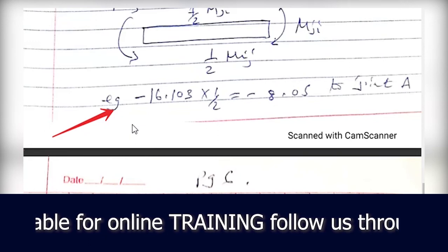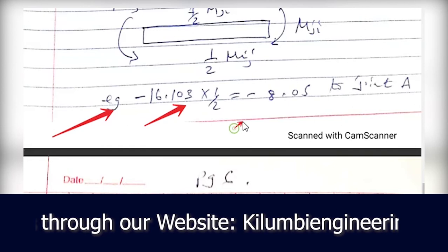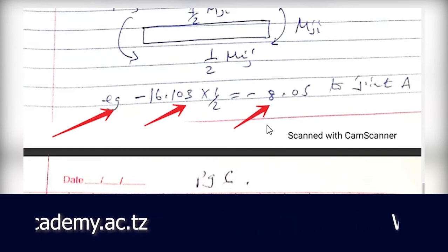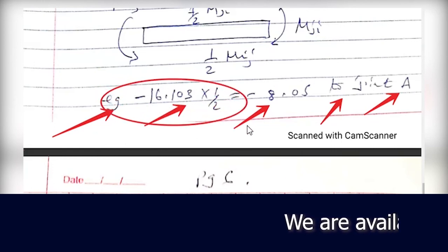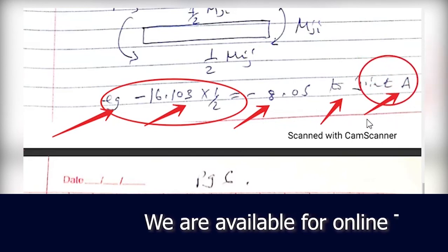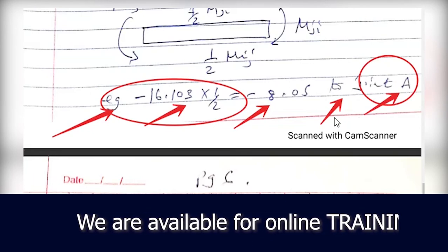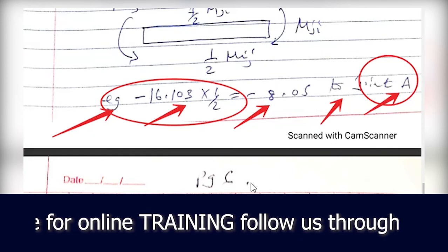Now negative 16.103 times a half should be negative 8.05 to be transferred or carried over to joint A, where this moment from the left is now transferred to joint A, which is the left one. So the same is transferred to that joint, it should be carried over. That's what we call the carryover moment. The same applies.